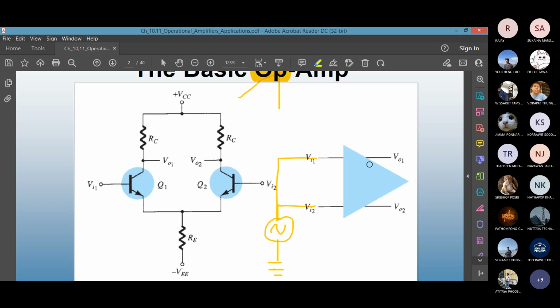What happens if you provide a common mode input signal? Common input signals result in opposite signals at each collector. So they cancel out. For the common mode input, the output of a differential amplifier ideally, meaning theoretically, should be 0, because one pin is called the plus pin and the other one is called the minus pin, which we'll study just a little bit later.